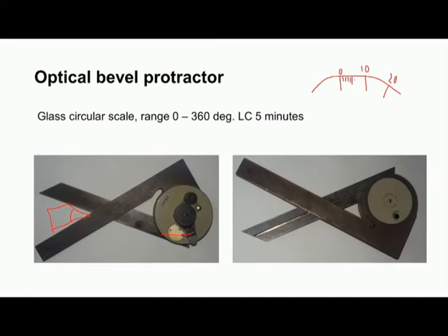So, this is 5 degree, again 6, 7, 8, 9, 10 like this, and then there will be a vernier. With 5 minutes at least count, with reference to this 0 on the vernier, we should take the main scale reading as well as the vernier reading, and then we can note down the inclination, the angle.